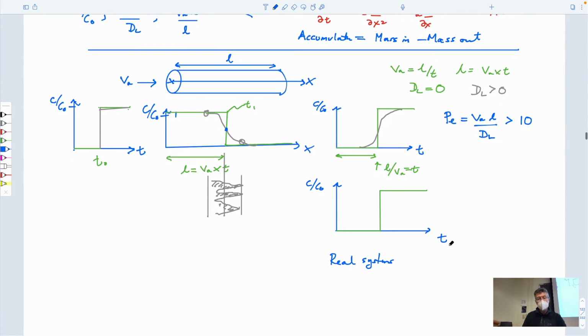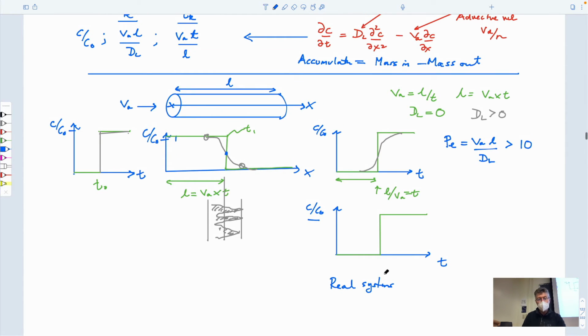And so what we can do is write this equation in terms of C over C0, which we said, T sub R. This is then equal to 1, which you can think of as if you introduce a dissolved tracer here at time 0. Once the water that you're pumping in from upstream has completely displaced the old water in this core, 1 pore volume, then it's arrived downstream at 1 pore volume, and the concentration should immediately go up to the stuff that you started pushing in.